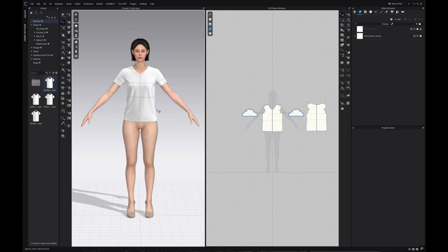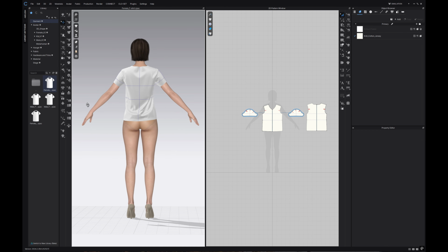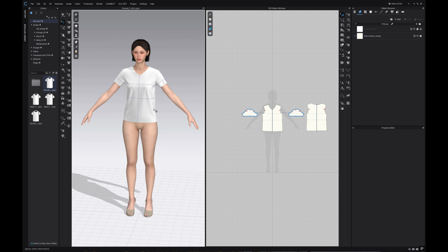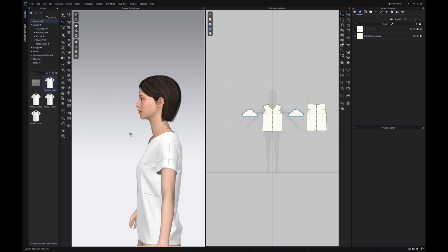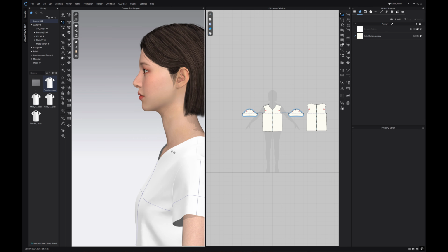Now, when you bring this into carbon and you run a carbon simulation with a knit cotton jersey material property, you get something very, very similar, as we'll see in a little while, to this. But there's one more aspect we need to consider, which is collision. The default settings give you a large gap between the avatar and the garment.